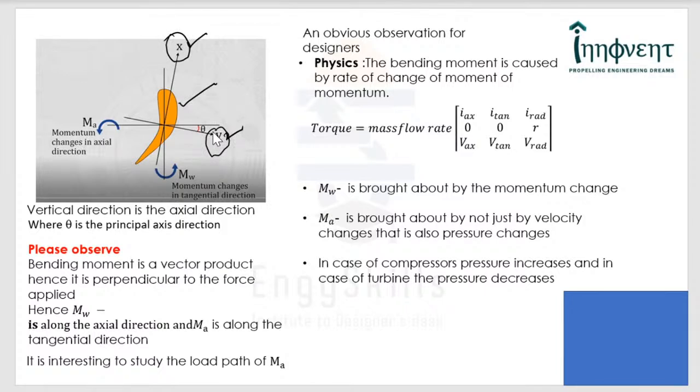For symmetric structures, these axes coincide with the actual geometric axis of symmetry. But since it's an asymmetric section, you have two principal axes of inertia. Here this is the x-axis, this is the y-axis, and it is obvious that the x-axis is the axis of minimum area moment of inertia, and this is the maximum area moment of inertia, right?